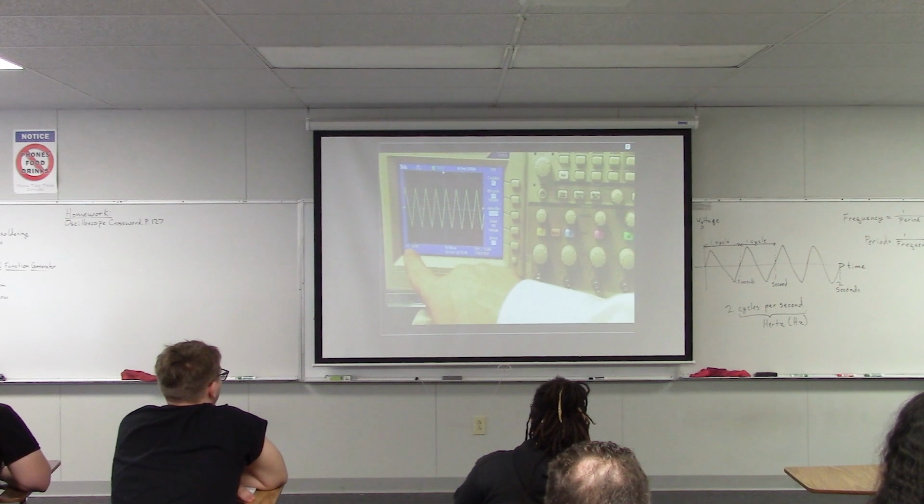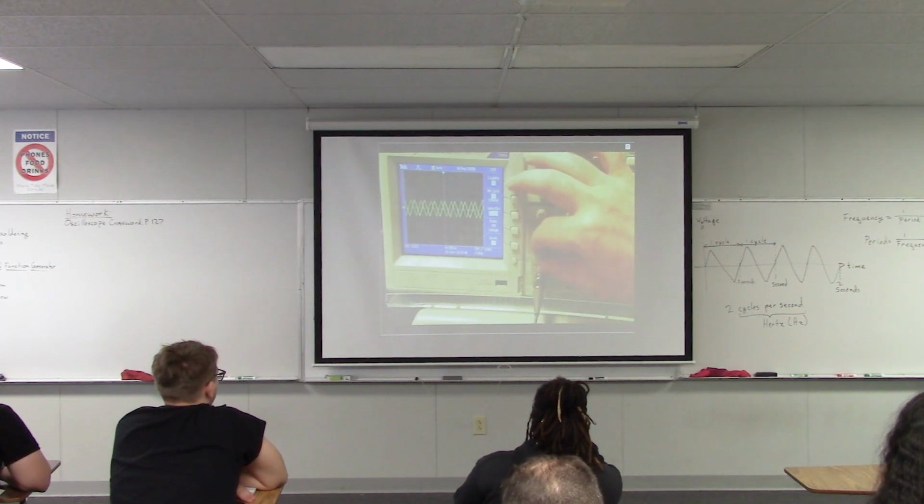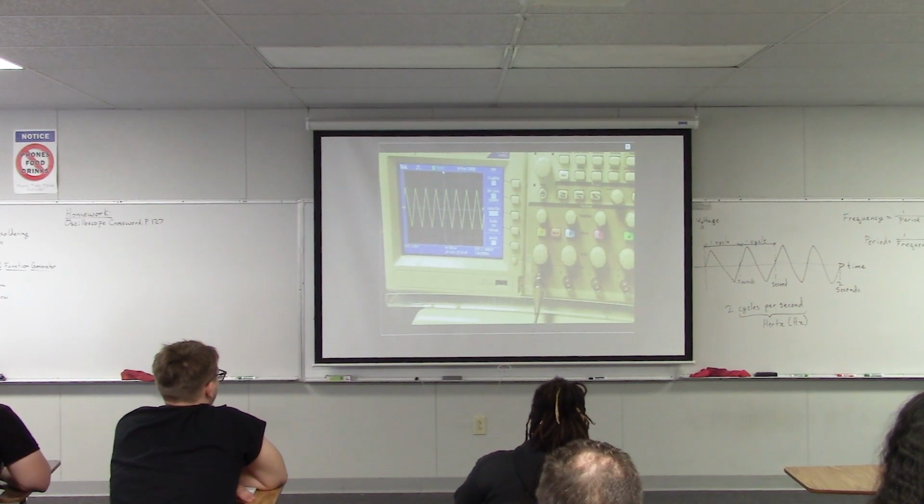So down here is the volts per division. Right. Okay. So right now it's set at 2 volts per division.